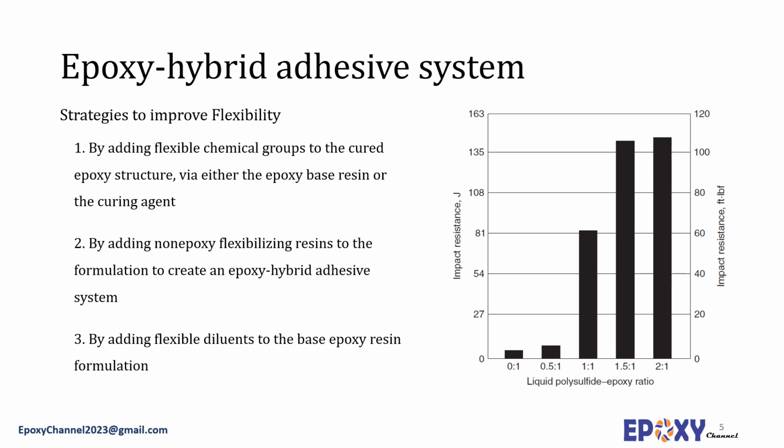A common technique of flexibilizing epoxy adhesives is by blending the epoxy resins with other more elastic polymers. Epoxy nylon, epoxy polysulfide, and to a certain extent epoxy urethane hybrids use such a mechanism to provide flexibility. It should be mentioned again that employing these resins may reduce certain properties. Flexible hybrid resins improve adhesive properties, especially low temperature performance and adhesion to flexible substrates. They also relieve stresses within the adhesives by allowing the chains to relax after cure, as well as any stress that can occur in the bonded joint during use.